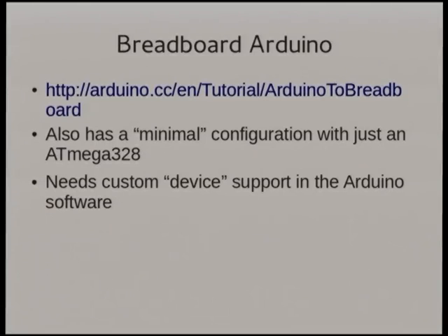So that's the breadboard Arduino that I mentioned before. It also has a minimal configuration without any of that supporting stuff, and it just needs a custom device added into the Arduino software. So if anyone remembers from the Leo stick last year, you had to open a text file and add a few extra lines into it so that you could actually compile and run apps for the Leo stick. It's the exact same thing. It's about 1 minute's work to add that in.